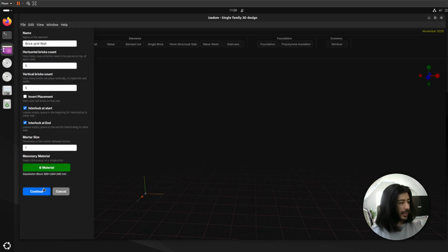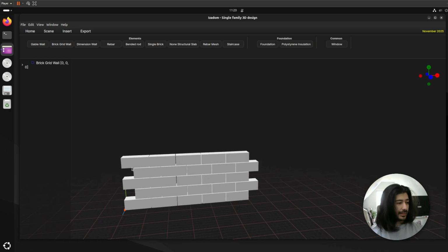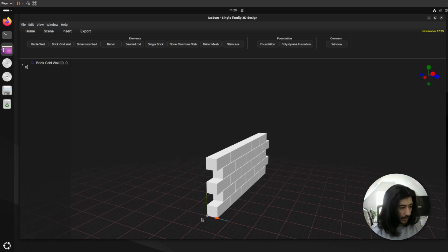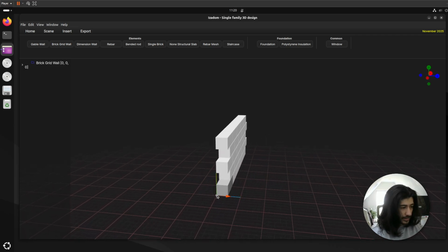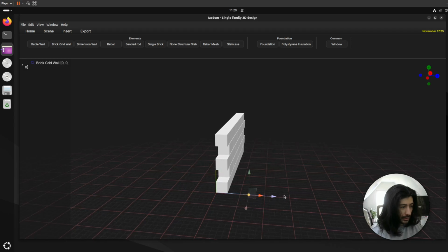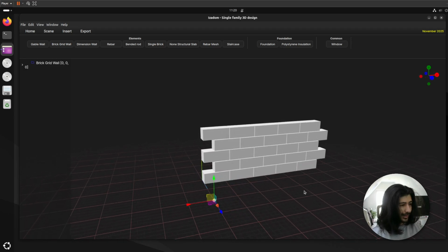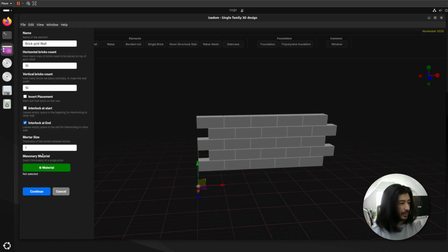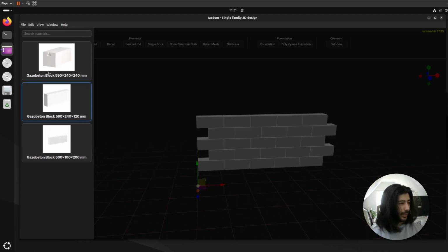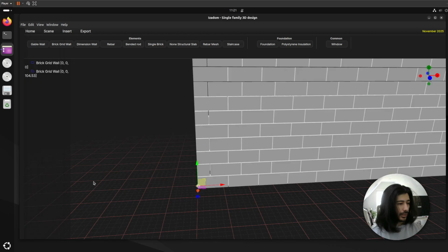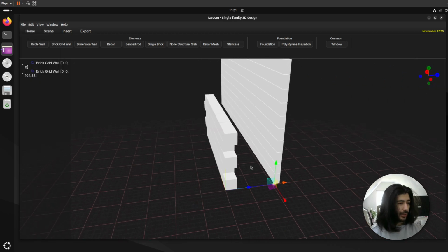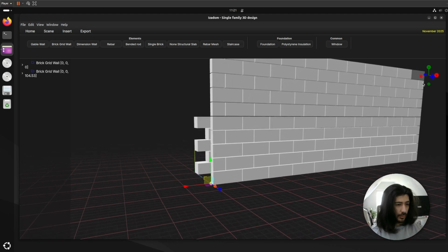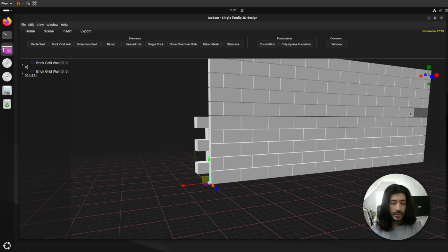So I'm gonna select that, create this wall. You see it has interlock in the start, interlock in the end. If I move this small pivot point, I can create the next element here. So I'm gonna go and create the brick wall and then do not interlock it at all. And I'm gonna use a different material and you will see now it is not having this interlocking option. It's pre-filled both on the end and in the front side.